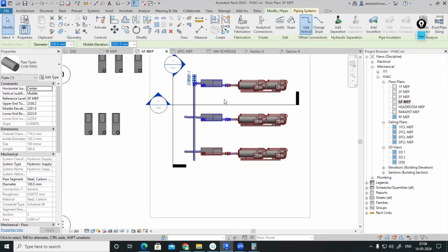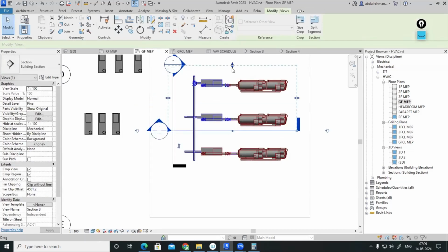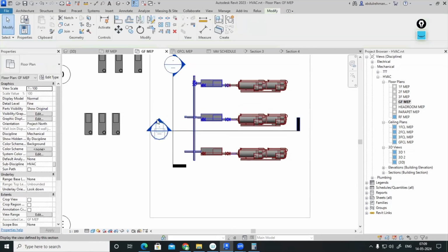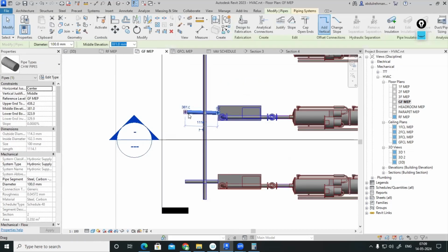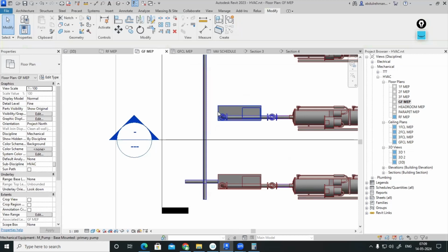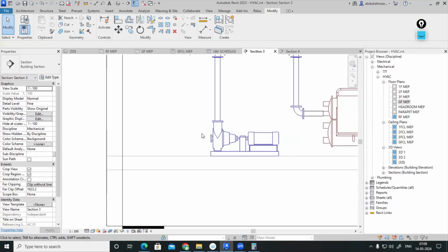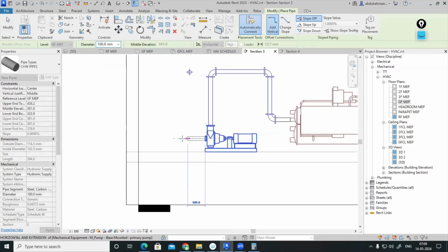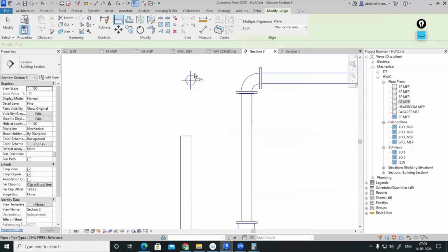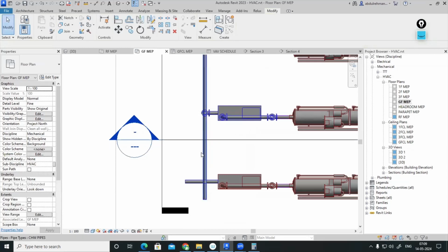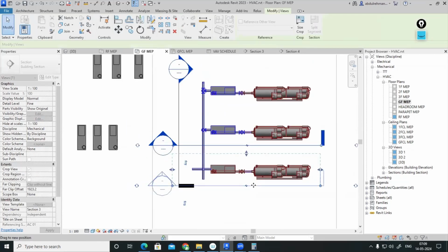And now all this has to be connected to the same pipe. I can make it like a straight pipe. Then I can connect it. But when I am making this as a straight one, in that pipe, I can connect my fittings. But it will consume a lot of spaces. That's why vertically we are taking it upside. Okay. Now I'll be selecting this one. Now we can align this one. Okay. With respect to this one, I have aligned it. The same way, this also.